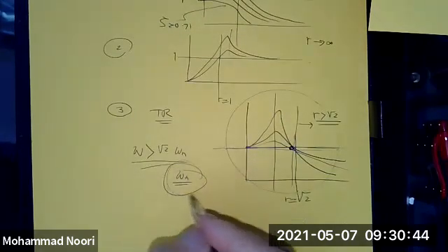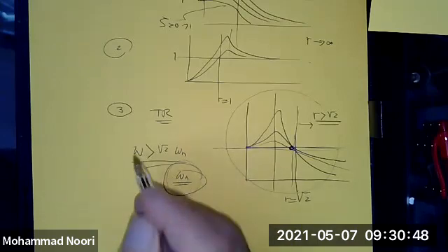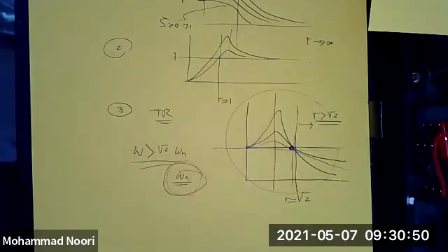The natural frequency should be much less than the frequency of the excitation, meaning the system should be as soft as possible, unless it is too soft, so that the static displacement is not too much. So this is, as I said, a very basic summary of what we have covered so far.